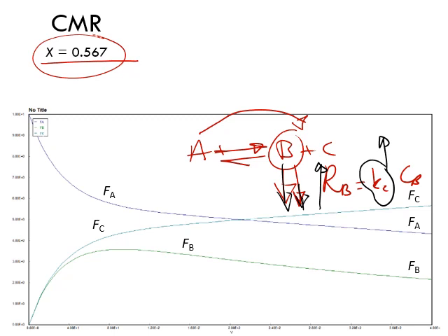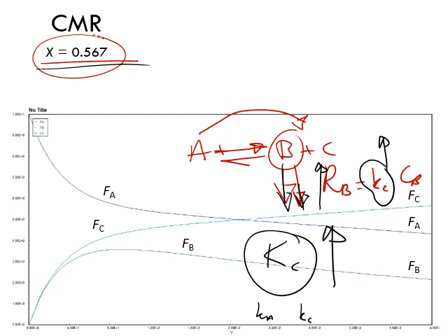Well, what about the capital KC? Again, the reaction is limited thermodynamically, so maybe if I operate at higher temperature, because this reaction is endothermic, at higher temperature the value of k is higher and luckily the value of KC is also higher. Okay, so if I operate at higher temperature, the value of KC will be higher, therefore the equilibrium will be shifted forward as well, and I'll be able to get more conversion.